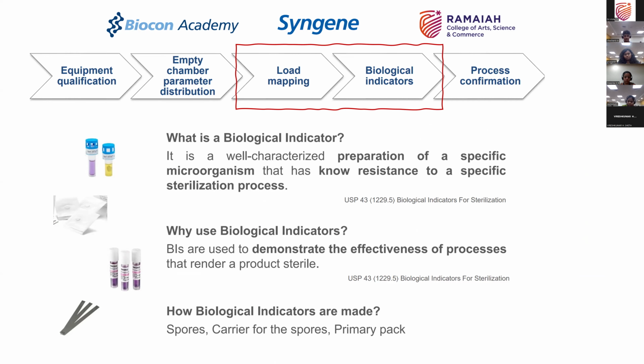Most likely, you will develop cycles on a fixed load, variable position basis. So, in the same situation, you look at penetration of the H2O2 by putting biological indicators, determine the difficult-to-sterilize loads, and use that as the effective measure by placing the biological indicators during the routine process.